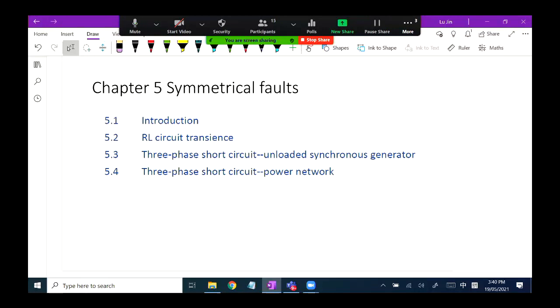But I hope you remember this procedure. That part is pretty tedious because you have to use a lot of KCL and KVL to determine the voltage for different components in the circuit. And then calculate that before the fault, after the fault, during the fault. So that part is pretty challenging in the calculation. Okay, so this is direct calculation, the first approach to this symmetrical fault. Because the direct calculation is hard, we introduced the second approach, which is the, you guys can remember that?